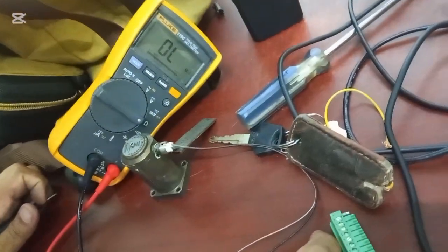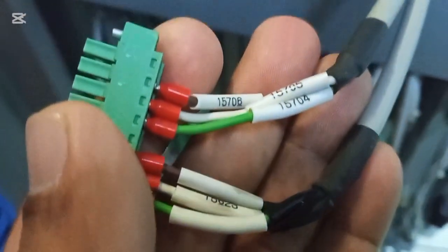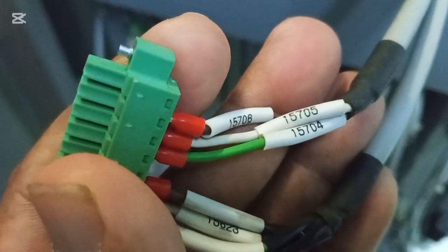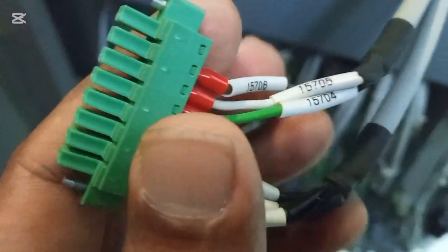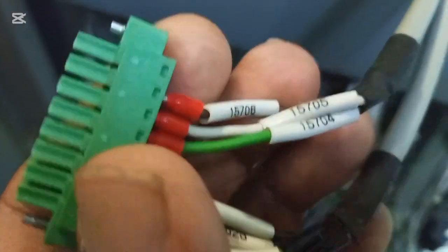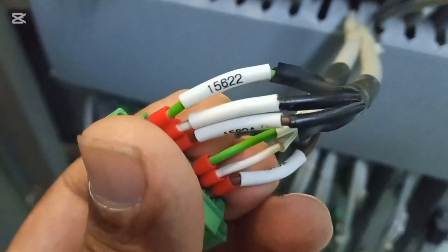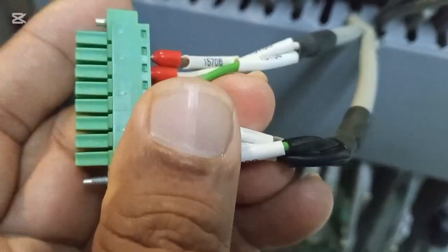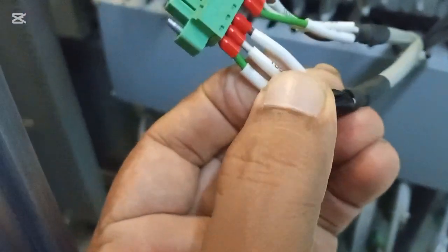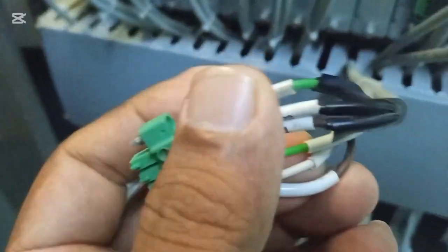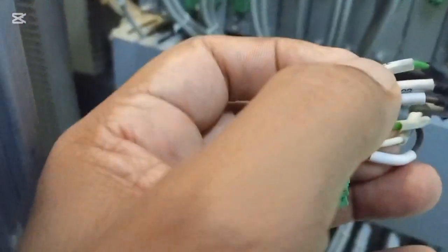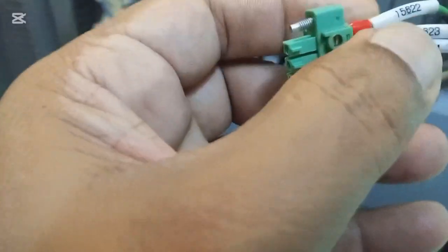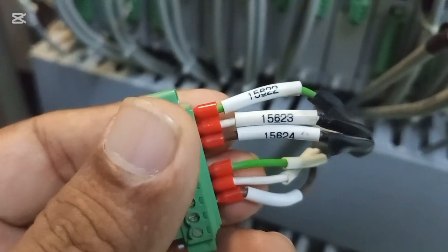We connected another new sensor to another base, and then we directly connected it to the Bentley system to check for a sensor fault or cable fault. After connecting the new sensor to this connector, and connecting this connector to the Bentley Nevada system, we saw that the vibration again exists. So we concluded that there is no sensor problem and also no cable problem.